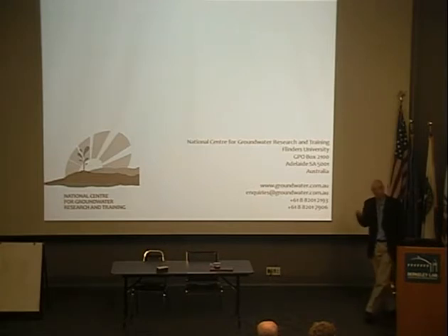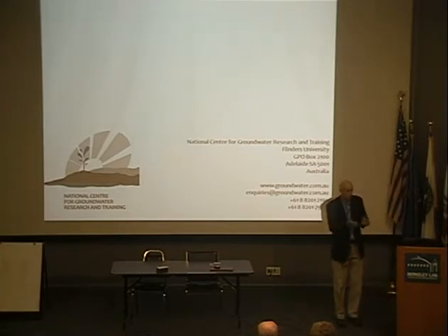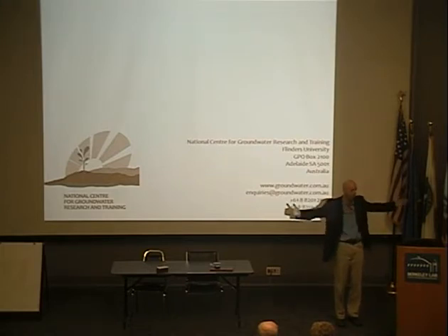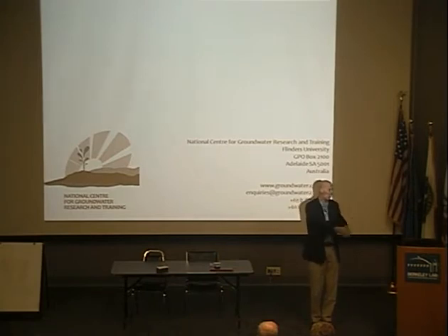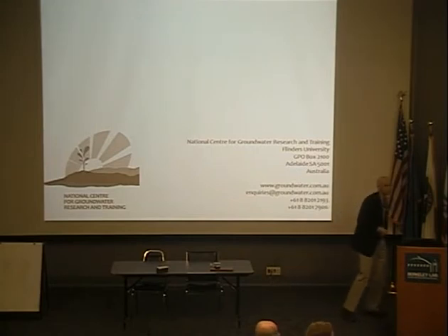We are making an assumption that when we take a concentration, the stream is perfectly mixed across, and that's a reasonably good assumption in the streams we work at, at the scales we work at. If you've got a concentration moving into a stream here and you're measuring the concentration over 50 metres downstream, you've got to worry about dispersion. At this scale, it's not an issue when we've looked at it. Just because the distribution is very small, so the dispersion term is very small in your case. Yeah.